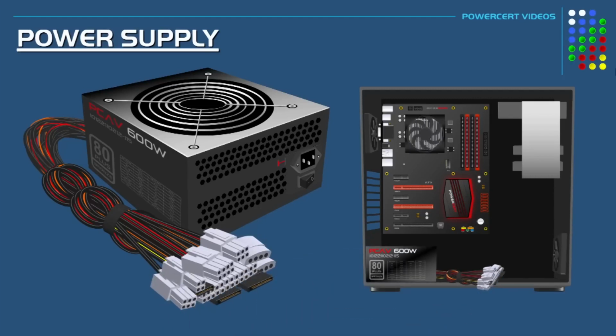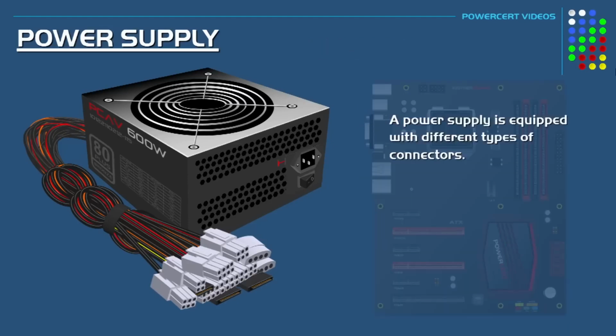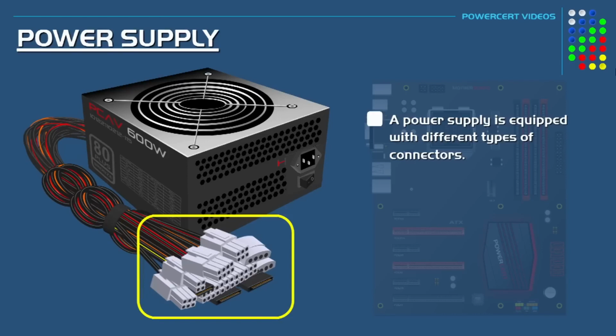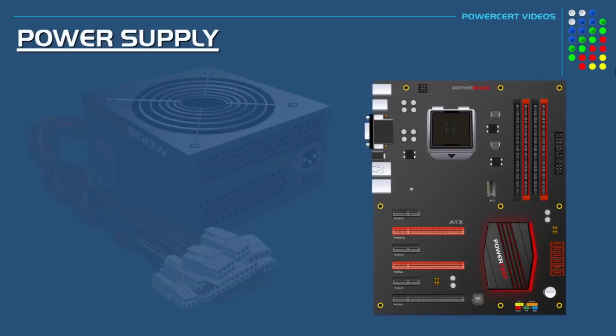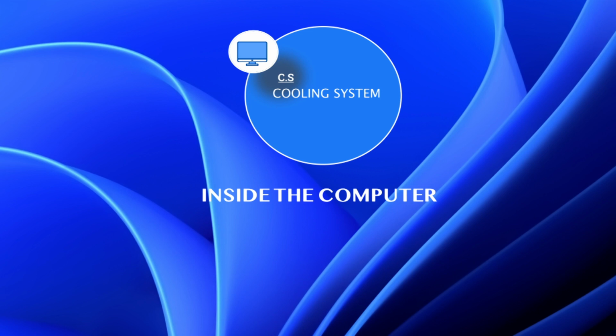Choosing a suitable power supply unit is crucial to ensure that a device or a computer system operates reliably and efficiently. It is essential to match the PSU's voltage, current, and wattage ratings to the power requirements of the components it will supply power to. Additionally, considering factors like efficiency, safety features, and form factors is important when selecting a power supply unit for a